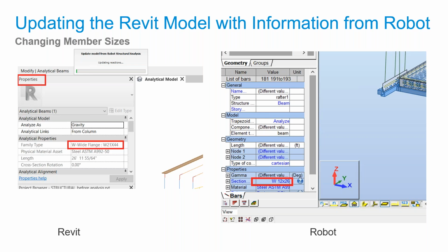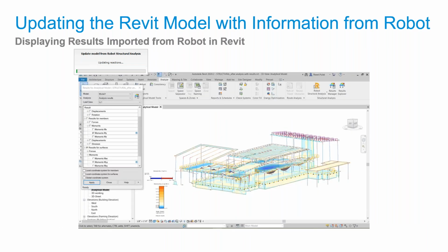And now what I will show you is how to display this result, because for a slab, when you want to put rebar on top of it, it's nice to have the needed reinforcement, so you can see if your rebar can be shorter, or if it's easier to use wire fabric or this kind of thing.